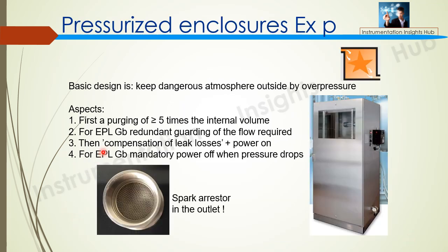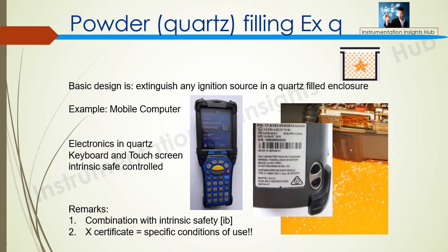All right. Pressurized: keep the dangerous atmosphere outside by overpressure in the container. Powder filling: basic design is to extinguish any ignition source in a quartz-filled enclosure. Example, mobile computer, electronics in quartz, keyboard or touch screen intrinsically safe and controlled.